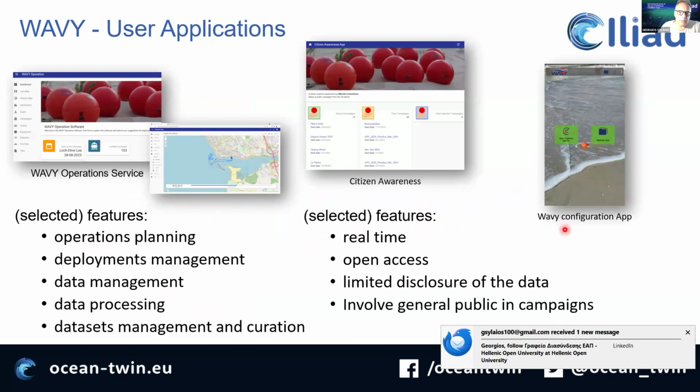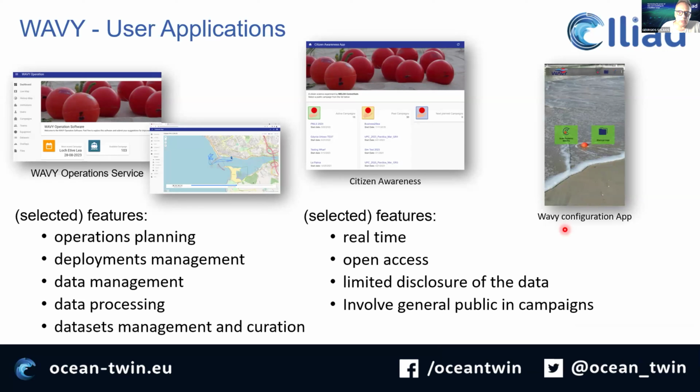Another system that my colleague Marco Oliveira will present to you in a moment are the Wavy drifters. They are again considered low cost. The cost, I think, is of the order of €1,000. So it gives us an understanding of the currents in a Lagrangian sense. All the other meters are located in one position, so they measure the currents in a Eulerian sense. Here, the drifter is moving passively with the currents, and it also moves up and down with the waves. So we have two types of measurements.